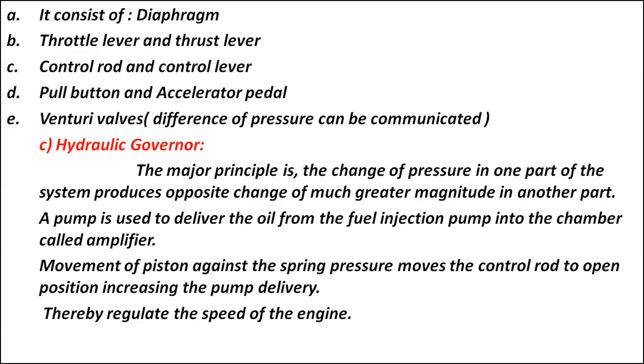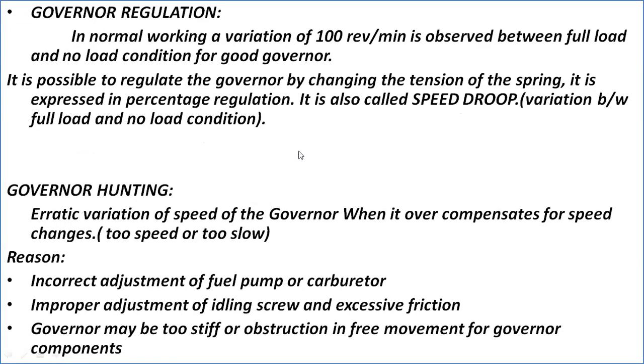The movement of the piston against the spring pressure helps the control rod to open the position and increases the pump delivery. The movement of the piston controls the position of the pump, the fuel injection delivery. That way we can regulate the speed of the engine.